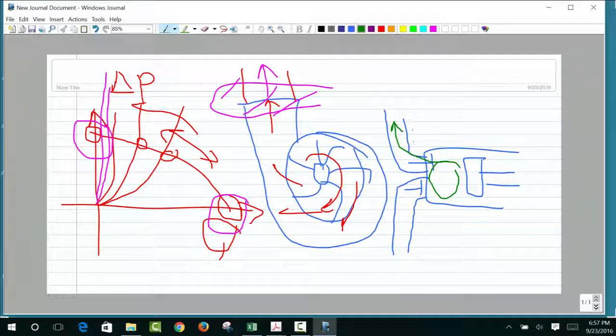Regardless of the pressure over here, this pressure could be high or low. The piston will have to either push the fluid against whatever pressure is here, or just break. The piston or the crankshaft rotating it, or whatever the mechanism, will just have to break if it cannot do the stroke. I mean, it needs to do the stroke and push the fluid. It cannot just stay because the pressure is high. There's no place to stay. The piston needs to push.